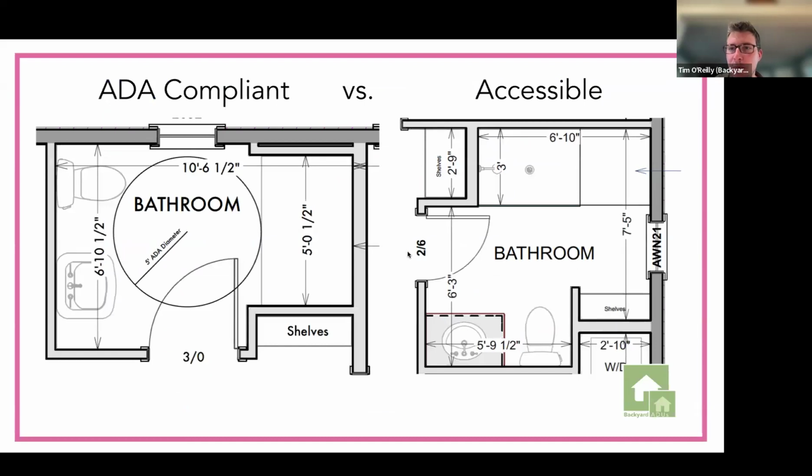Getting into the nitty gritty of the bathroom. This is what I mean by an ADA bathroom. On the left, there's a 5-foot diameter circle. And so you can see that's awesome in a wheelchair. You're going to be able to move and maneuver. There's also shown here, it's hard in this view, a pedestal sink. So you'd have no problem rolling right up to it and using it. But that is a lot of clear space. And when we're designing in a small space, every square foot matters. So if you want the ADA, it is possible. That may eat into your living room. You may not be able to fit an oversized armchair and a couch if we're taking a couple extra square feet to the bathroom where it might be needed.